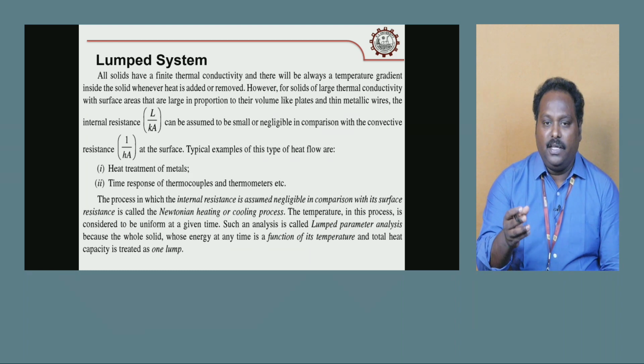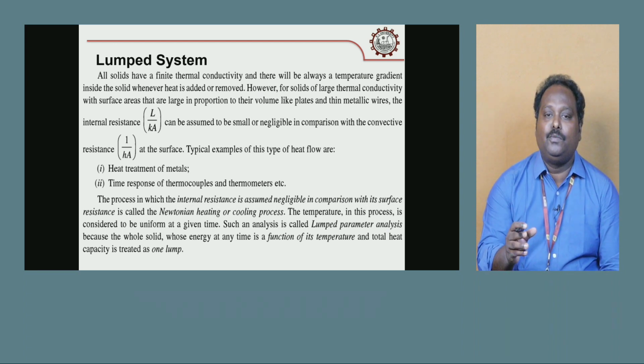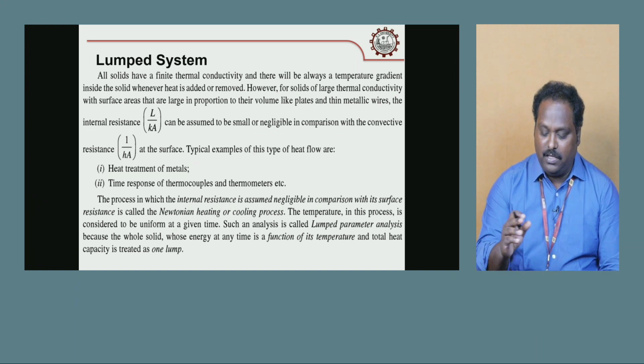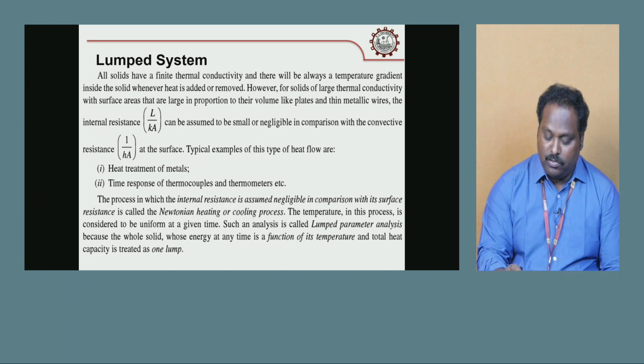So in lumped system analysis, throughout this process the temperature throughout the solid is assumed to be uniform. That means the temperature should be uniform throughout the entire mass. So when internal resistance is negligible, the temperature inside the solid is uniform at any point of the mass.